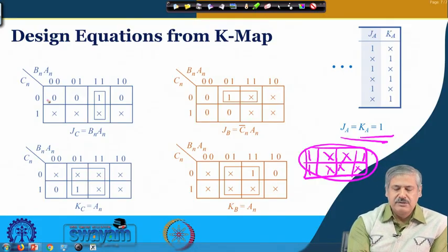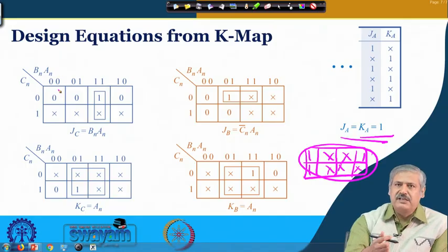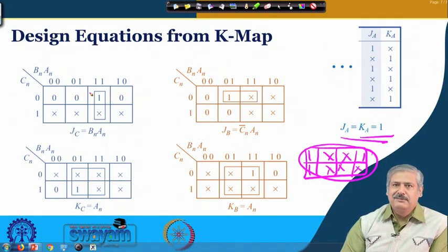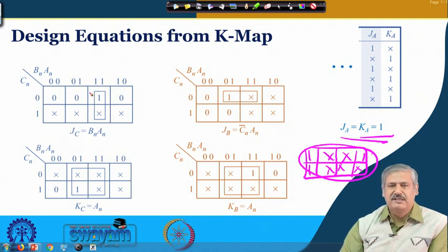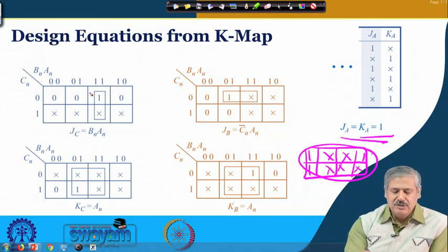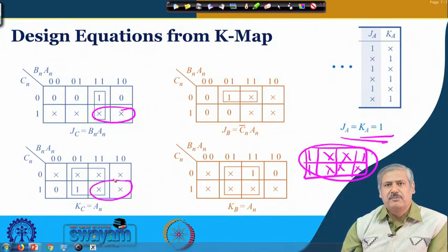For other cases we are just substituting the values, taking the values from those columns, and remember this 1 1 0 and 1 1 1, those were not there. Those last two, with 3 flip flops, 8 possible states are there. So 1 1 0 and 1 1 1 we didn't consider, right? It is not a valid state, isn't it? So we consider for those two cases cross cross. That means it doesn't matter, because it is considered that it will never go to those states. Okay. So it is initialized with one of the valid states.